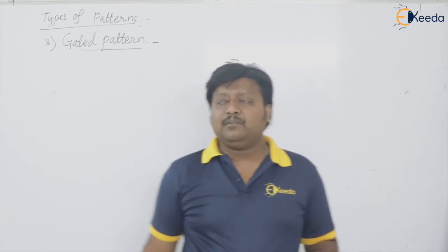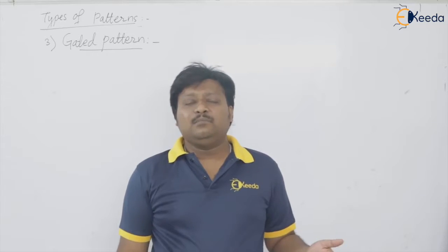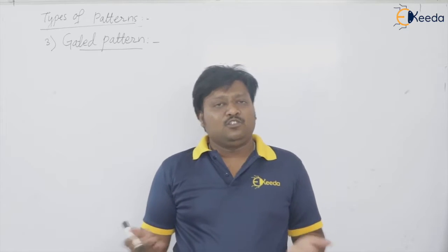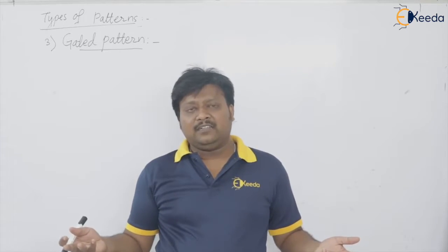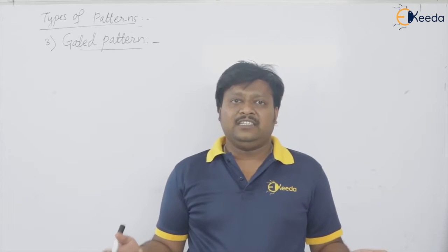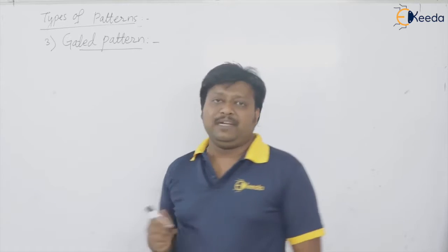So what is meant by gated pattern? This is, I can say, the extension of the simple or single piece pattern where the pattern is along with the gating and risering system. So the mold maker need not cut that by hand. So definitely the production rate of making the mold is going to increase. So this is the gated pattern.